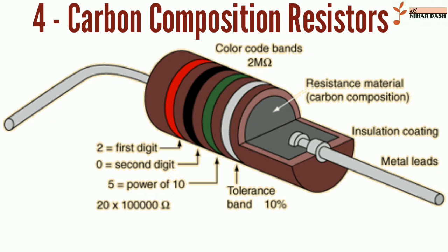Carbon composition resistors change value when stressed with over-voltages. Moreover, if internal moisture content, from exposure for some length of time to a humid environment, is significant, soldering heat creates a non-reversible change in resistance value. Carbon composition resistors have poor stability with time and were consequently factory sorted to, at best, only 5% tolerance.